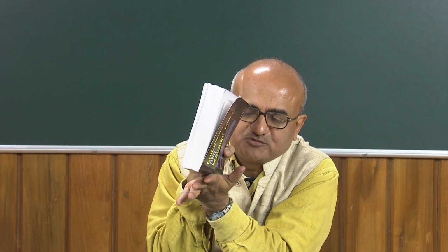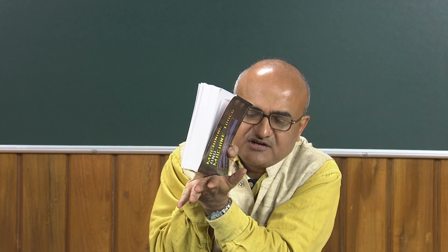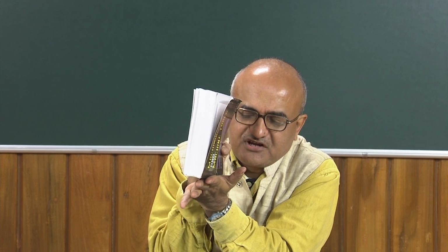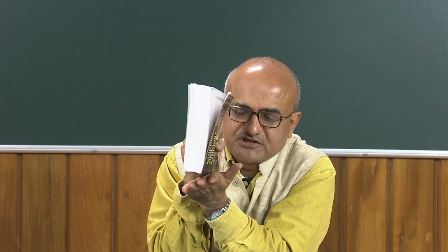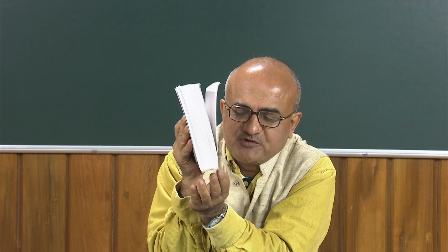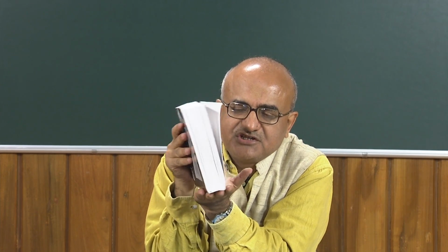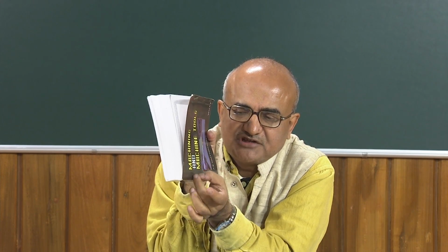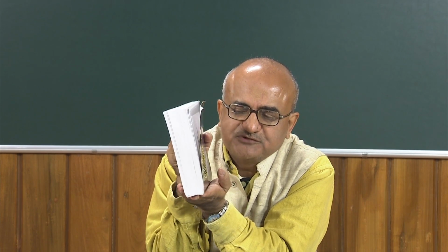So it is better to provide some inclination here also, then it can do proper cutting, and this surface will not be rubbing against the machined surface or against the surface of the workpiece. So that means we have to give the clearance angle. At least these two angles, that means rake angle and clearance angle, I have explained here.